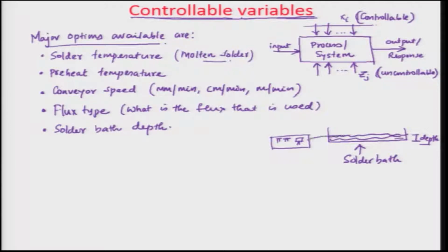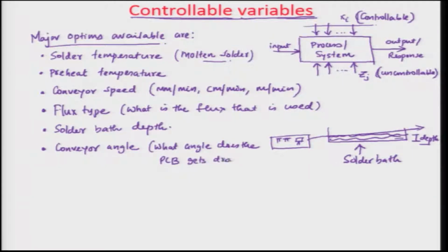and this gets dragged along this one. Okay, so that's another option, right? Then another possible option is the conveyor angle. Okay, depending upon what angle the PCB gets dragged in the solder bath. Okay, so that is one option that we have.